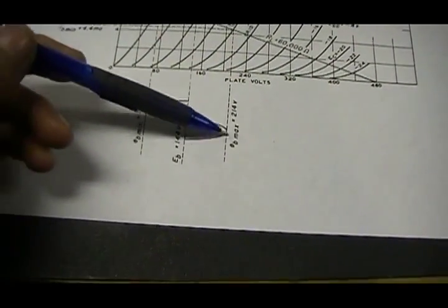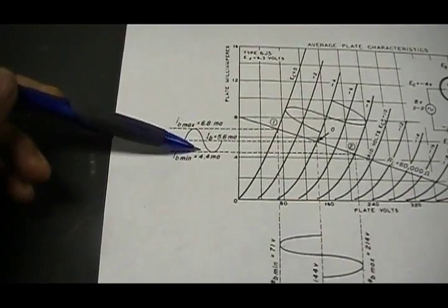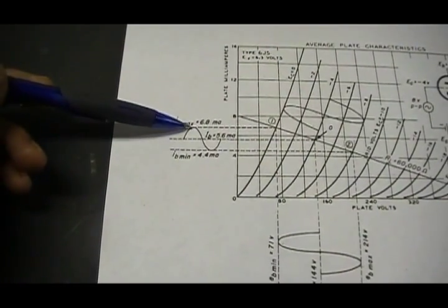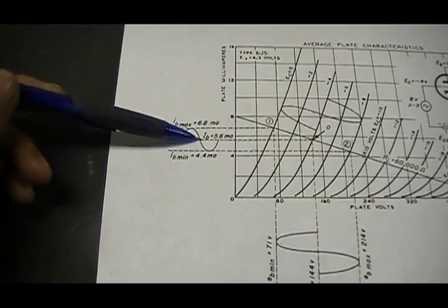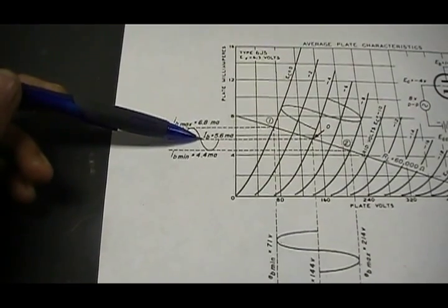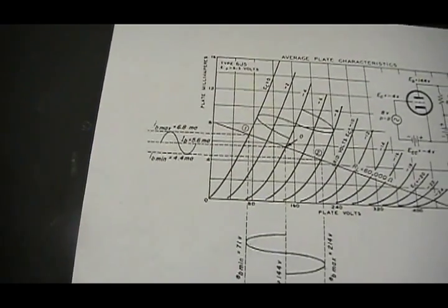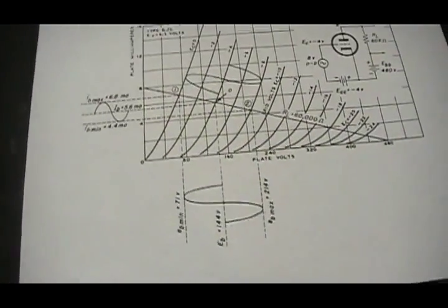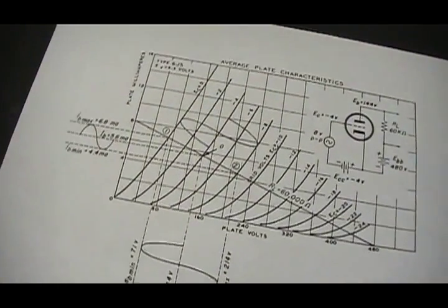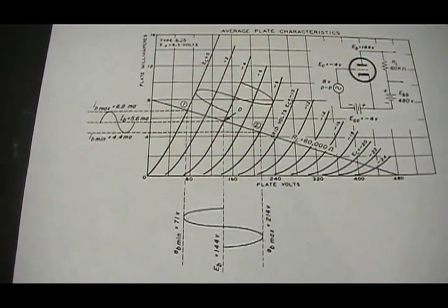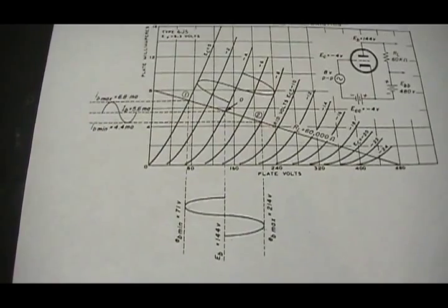So you can either take the voltage or the current and do the math. Simply subtract the no signal current from its max and from its min, and if they're fairly equal or are equal, actually if they're equal, it'll have zero harmonic distortion in it.